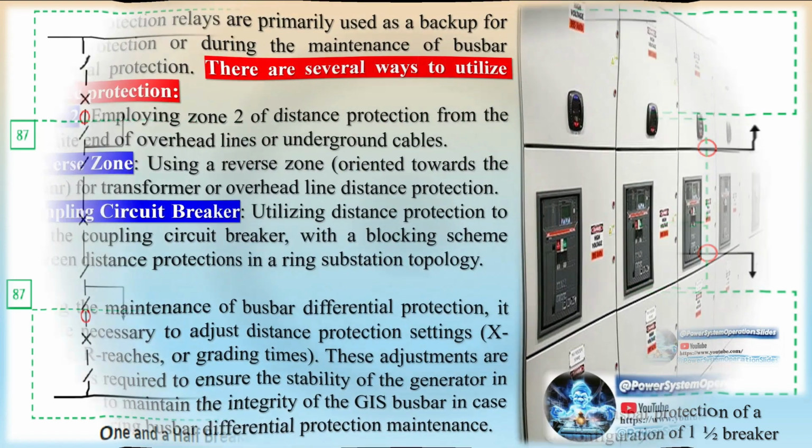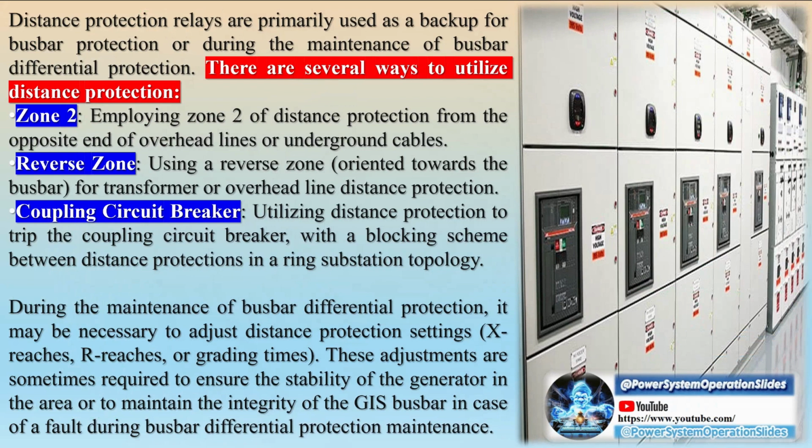Arc fault protection is used for the rapid clearance of arcing faults in busbars, circuit breaker compartments, and associated cable boxes in air-insulated metal-clad medium and low-voltage switchgear. Arc flash detection methods. Arcing faults release large amounts of radiant energy, including light and thermal energy. The light intensity from an arc can be thousands of times higher than normal ambient light.